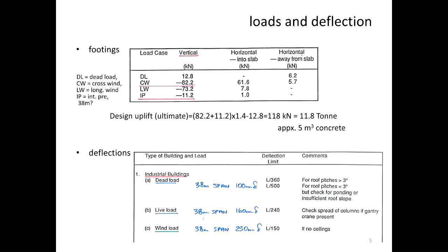Okay? So generally, for serviceability, we have to consider, as I said, the deflection ability, how much the building can deflect. With every building, we can allow the building to deflect a certain amount. So when you have wind blowing on a structure, the building itself will deflect within its serviceability limit, but it's so small that you will not see it. So when we do our design check, we have to ensure that that is being done.